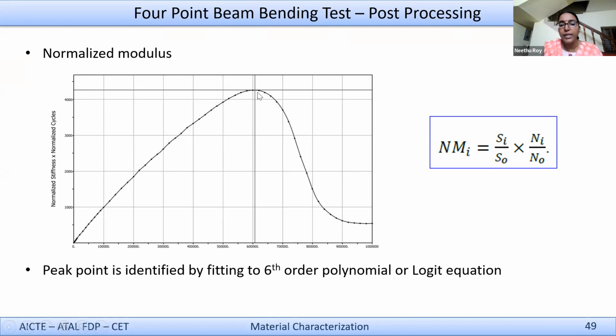It will reach a peak point, and this peak point will give you the fatigue life of the mixture, right? So you can either look at it like this, or again, as in the case of rutting, you can fit a polynomial or a logit model to this to see what this peak point is.